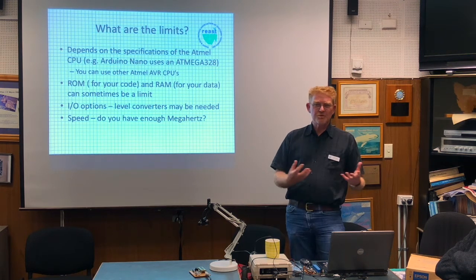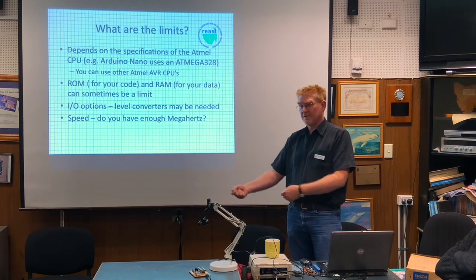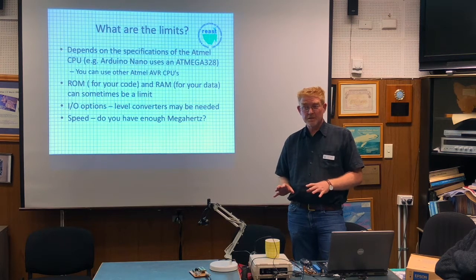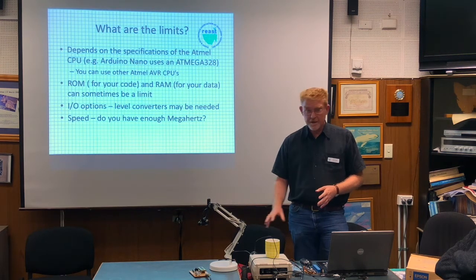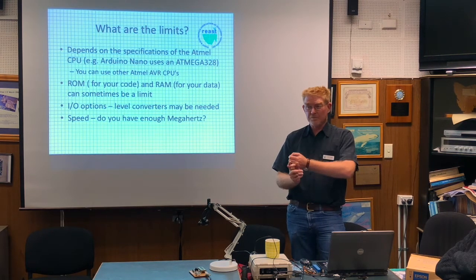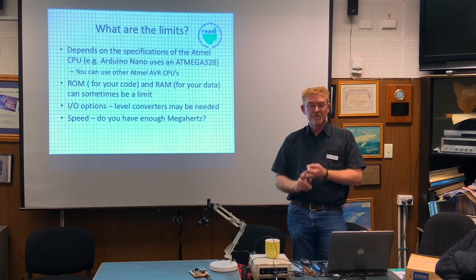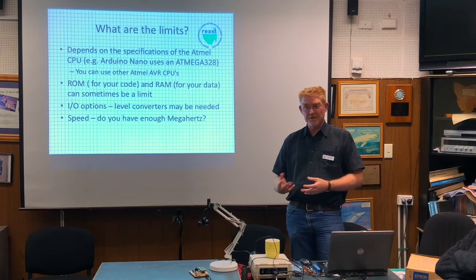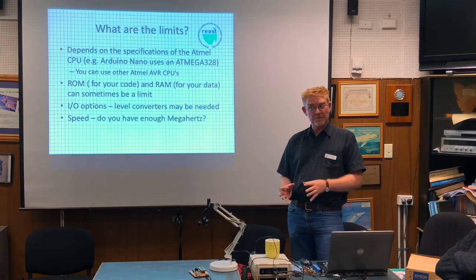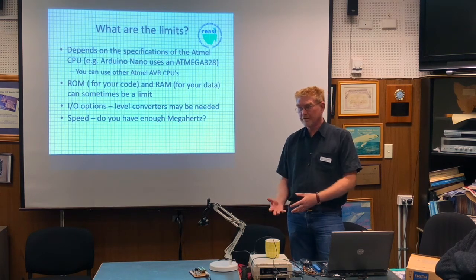Or sometimes you can talk over Ethernet, but you need another chip to do the heavy lifting for you, and you talk to it and it talks to the network. So, kind of clever. There's not a lot of RAM on these things. The Arduinos we'll show you here have about 2 kilobytes of RAM. That's for the stack, for temporary variables, for things like buffers, for input from users, for forming information with displays. 2K is not a lot of memory. So again, when you're writing code, you look at what's going on in your code and you're economical about it. Or you just get a bigger chip than the one you're using and work your way around those limits.